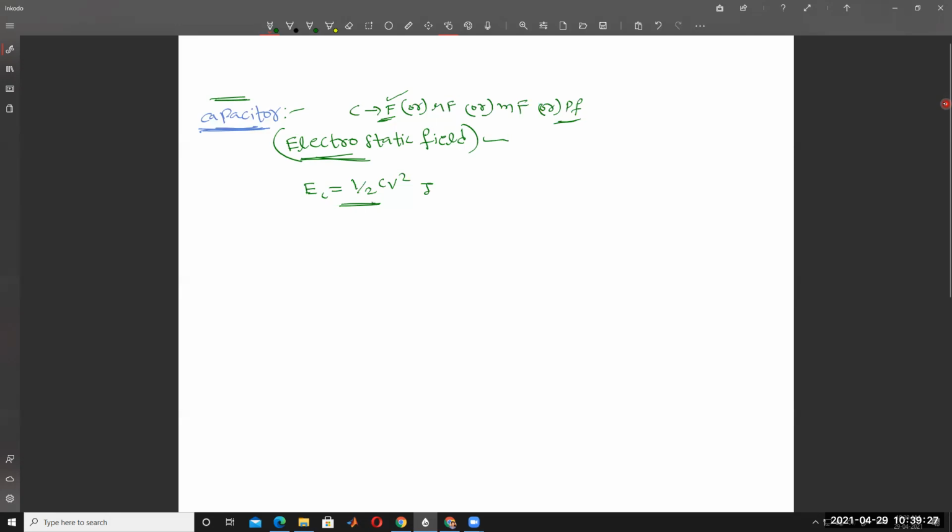So this is called a capacitor. The current flowing to the capacitor is IC. The voltage across the capacitor is called VC. So the current flowing to the capacitor, IC, is equal to C into dVc by dt. Understand? And this capacitor does not allow sudden changes in voltage.